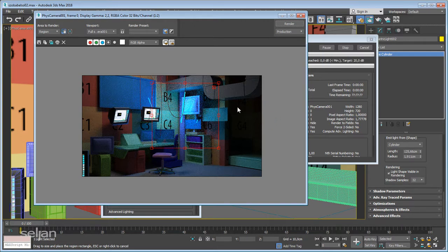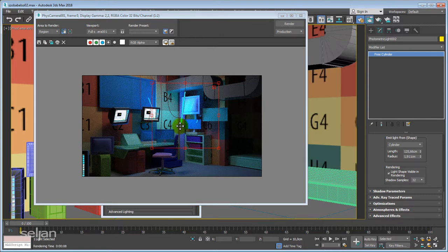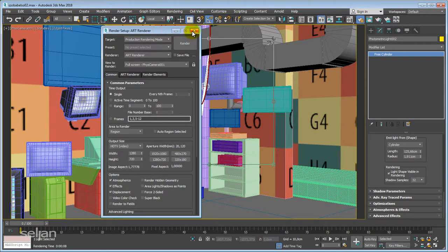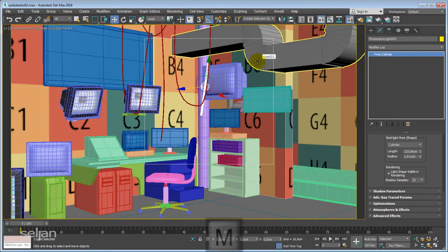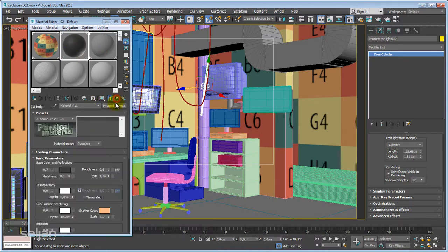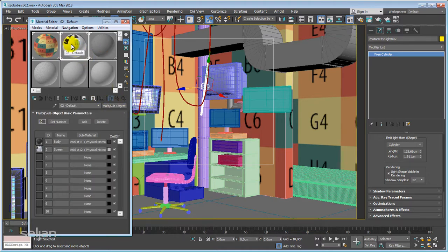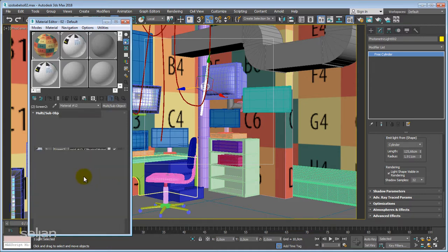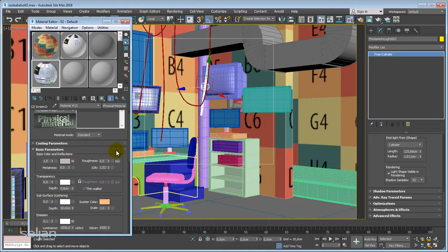Okay, if you have different screens, different TV screens, you might want to create different materials. The easiest way to create a different material is by opening up Material Editor, and selecting the original one, going to the highest level, and you can drag and drop it. Right now you have the same material as a copy, and you can go in and change the name, for example, screen 2, then going in and switch the material that you want to use and drag and drop it onto your new model. Okay, technically that's it.